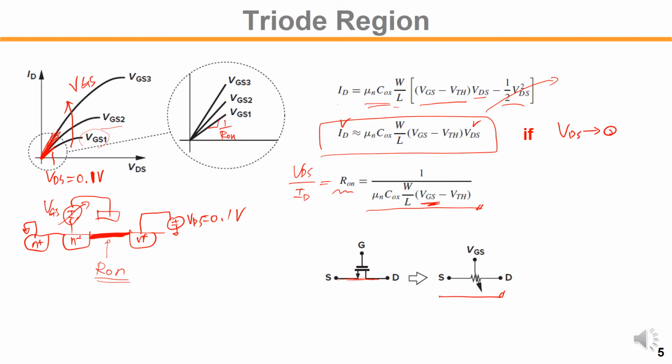Now if you increase VDS even higher, there is some point where the current doesn't increase anymore. It becomes nonlinear, the current is compressed and saturated for larger VDS. Why is this current saturated? We will see it later. This kind of current saturation causes some nonlinearity.